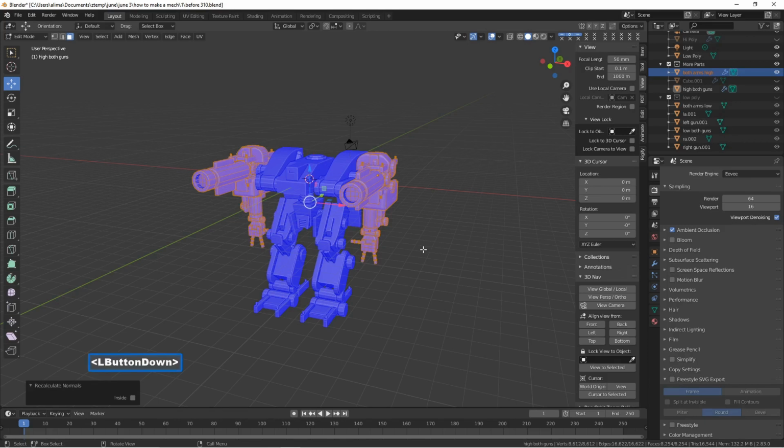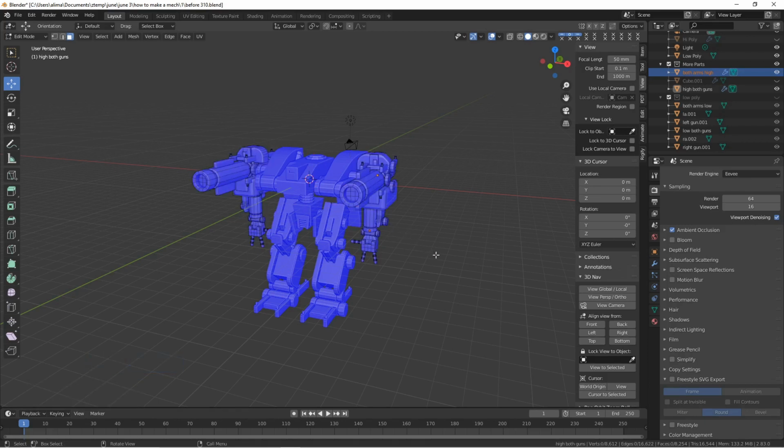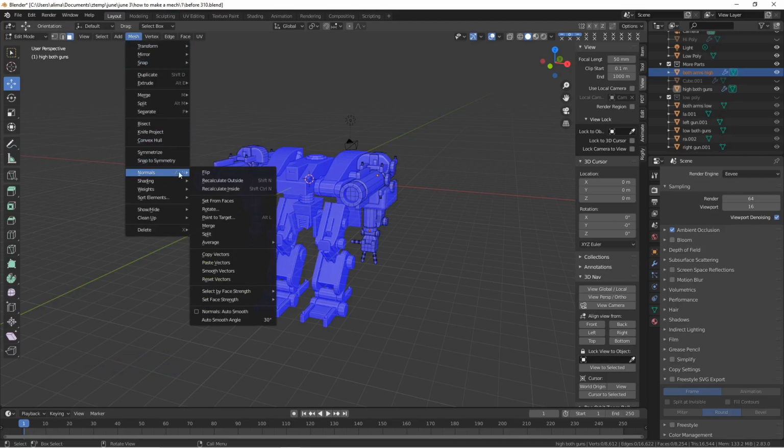So basically what was going on is our normals were not right. When we tried to bake our objects, we would have had issues because the normals weren't right. We pressed Shift N, which recalculated the normals. The fact that the model is showing blue now shows us that our normals are correct. Normals face the proper direction, is how you can think of them. We could have gone to Mesh and then Normals, and then recalculated the normals. We used Shift N as a shortcut for recalculate normals instead.